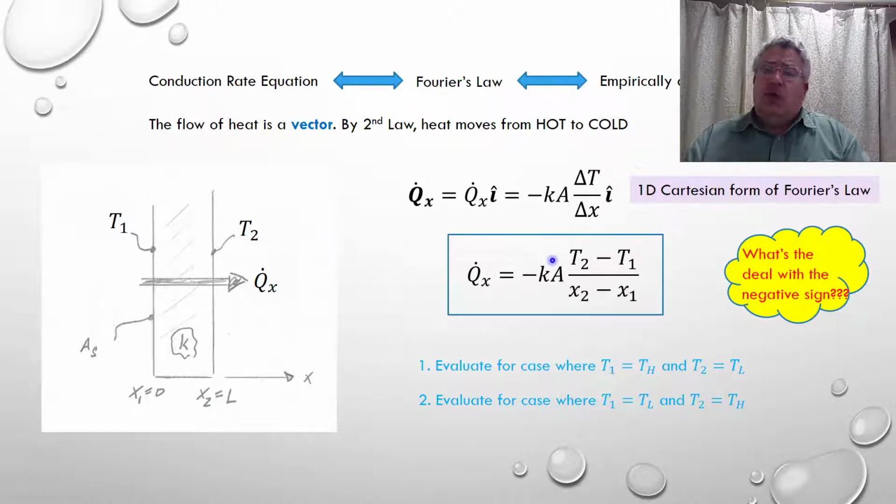And what we're essentially doing, right, delta T over delta x is the slope of a line. So we're going to go the rise over the run. So from T1 to T2, the rise is T2 minus T1. The run is x2 minus x1. All right, so that defines our Fourier's law for this situation. Now let's evaluate it for different cases.